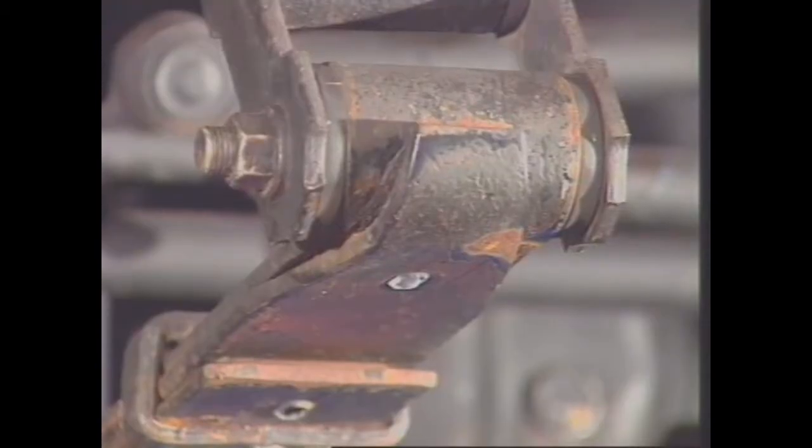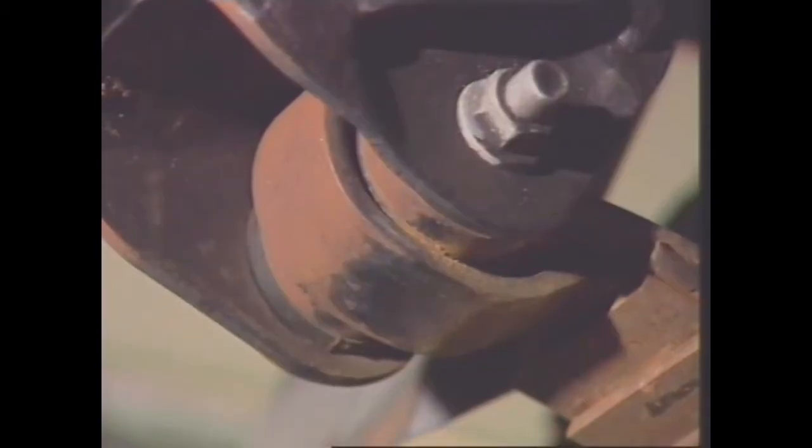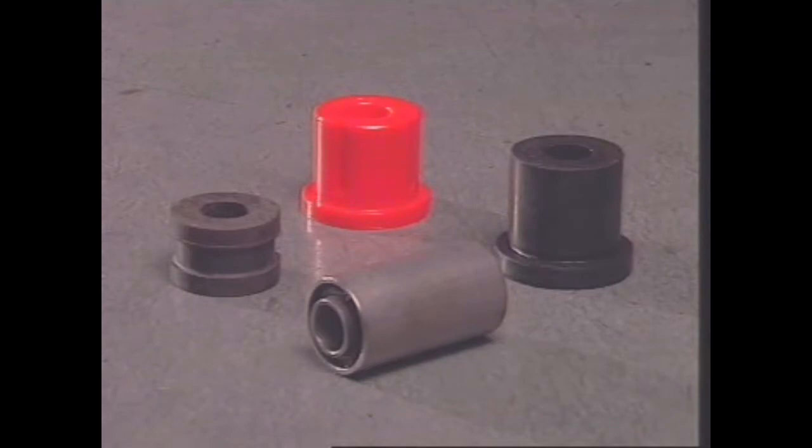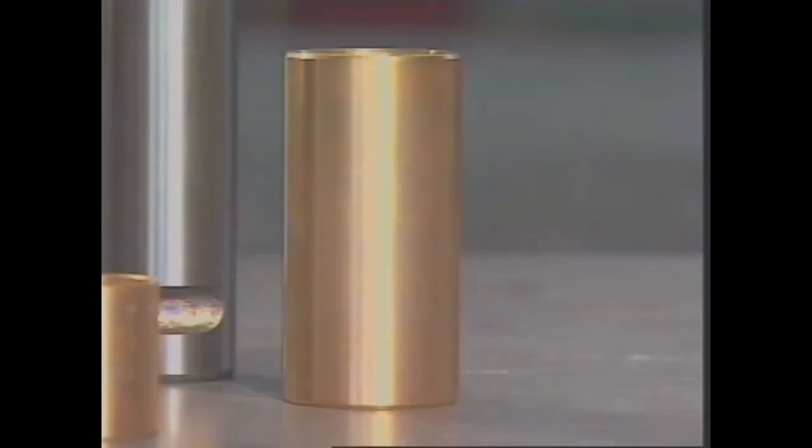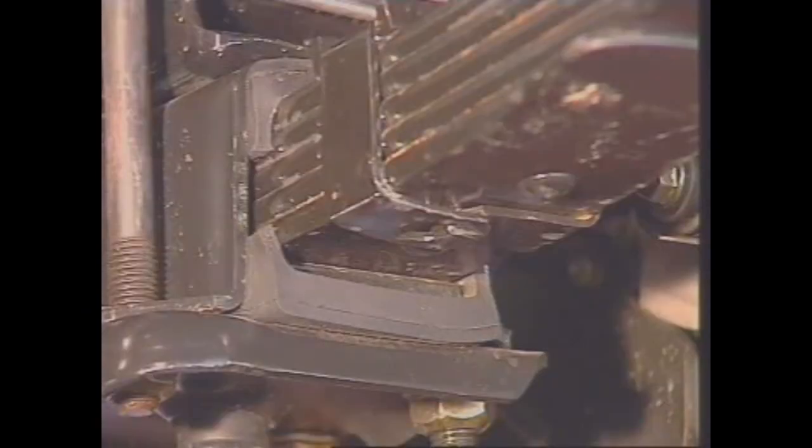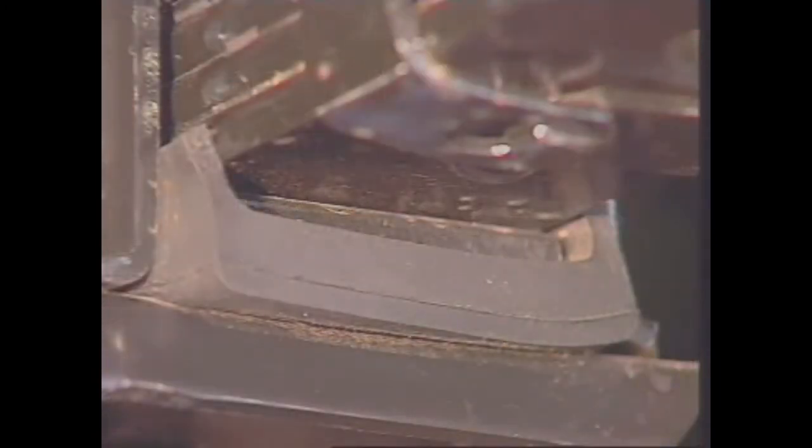Some springs have inserts between the leaves of plastic, nylon, or rubber. They act as insulators to reduce noise transfer and friction as the leaves move under load. Some older vehicles completely enclose the leaf springs in grease. The spring eyes are fitted with bushes, usually with a rubber, flexible section. But nylon and urethane bushes are also used, and sometimes bronze for heavy-duty applications. Rubber insulating pads between the spring mounting pad and the spring also act as insulators. And similarly, between the spring plate and the spring.